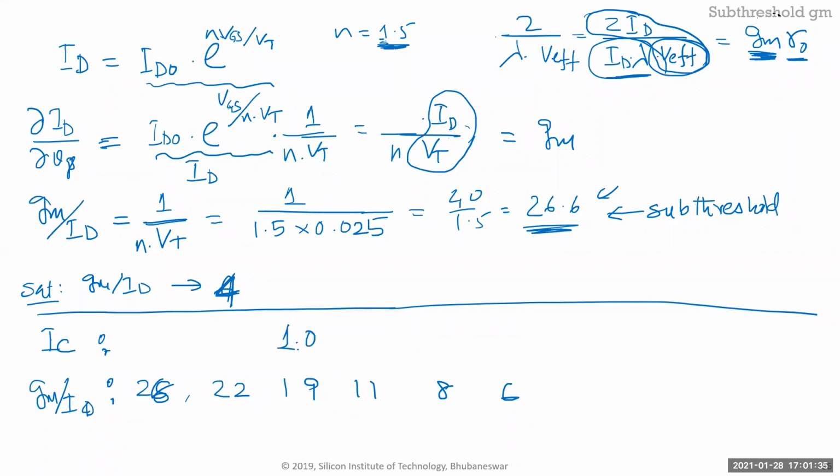So 1.0. This point tells you if it is inverted or not. When your channel just inverts, your inversion coefficient is 1.0. Anything lower than that, the channel is not inverted. So for 22, it's about 0.5. For 28 it's about 0.1. Then for 11, it's about 5. Like I said, I'll send you a link to a paper which has this equation.